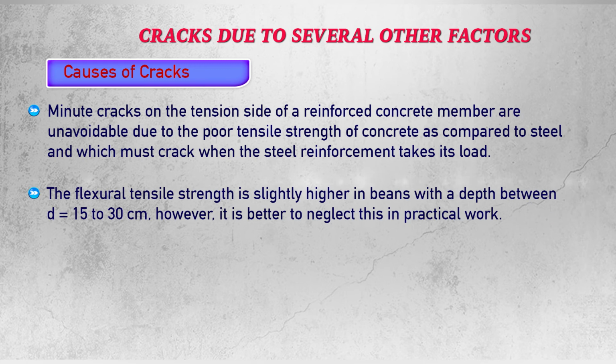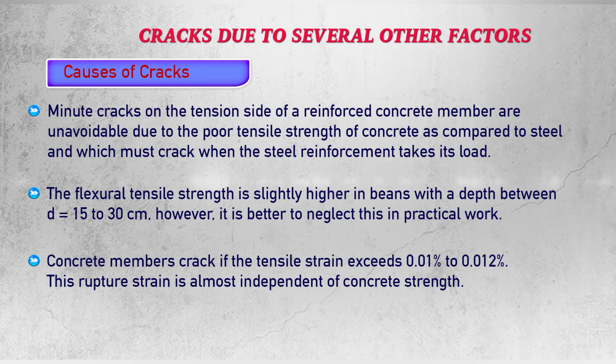The flexural tensile strength is slightly higher in beams with a depth between 15 to 30 centimeters. However, it is better to neglect this in practical work. Concrete members crack if the tensile strain exceeds 0.01% to 0.012%. This rupture strain is almost independent of concrete strength.